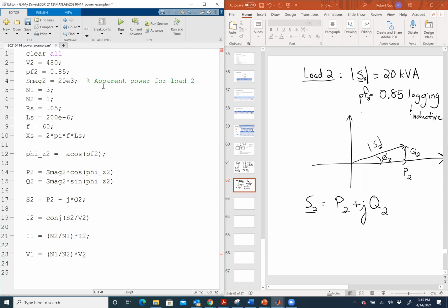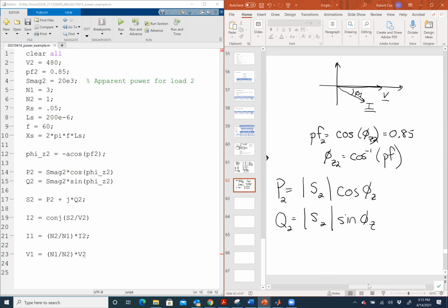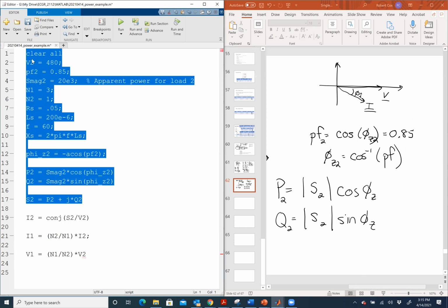If I want inverse trig functions in Matlab, it's atan, asin, acos. So acos, atan is the way that's written out. Then I wrote out my P and my Q stuff here, just like I did over here. I'll give you guys this file. These two go together, and then I put them together into one vector. So let's see what I got when I did that.